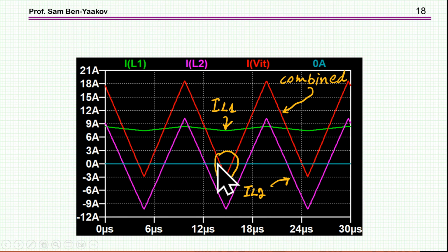So if the magnitude of the ripple is made correctly, we can get this current reversal, and therefore this converter will operate like in the normal BCM, except that the current that the midpoint sees is now not just the inductor current, but actually it's coming from the two inductors and being combined to get what we need for soft switching. So this is the idea.